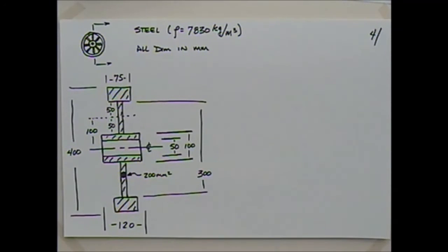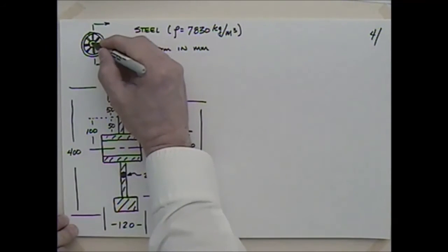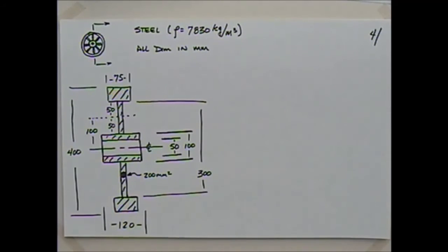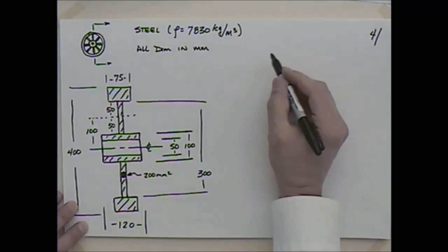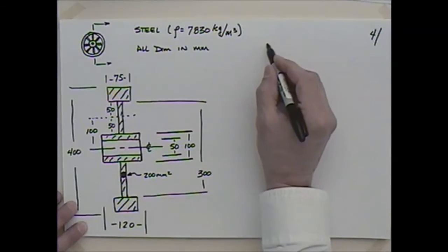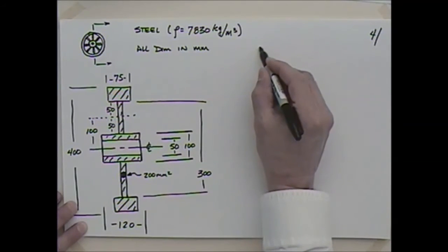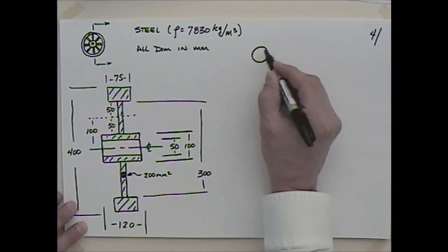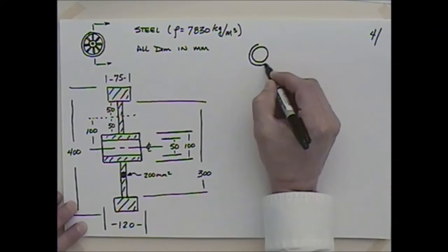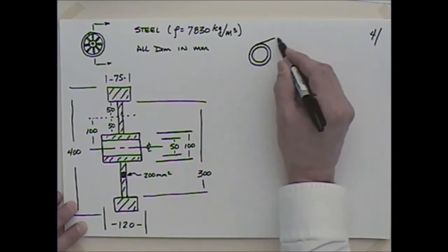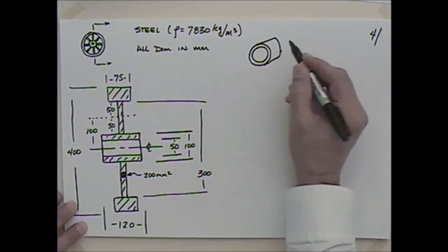So we'd like to come up with the mass moment of inertia about this center line, about this axis that's going through this hub. If we were to put that hub on a shaft, what would its mass moment of inertia about that be? And one of the things that I probably need to use is I need to figure out the I for a ring. So if I look at this, and it's got some distance here,